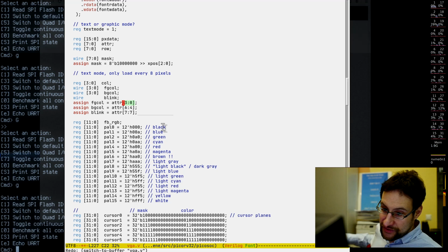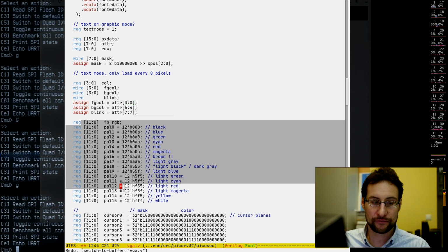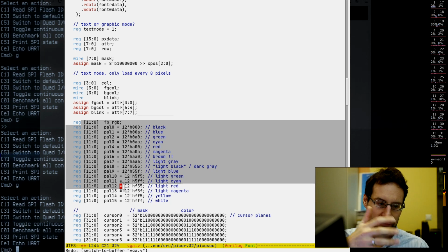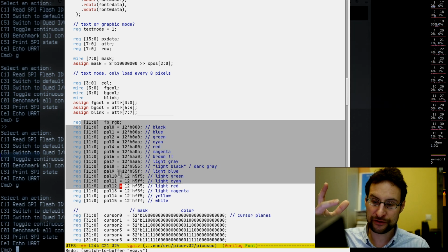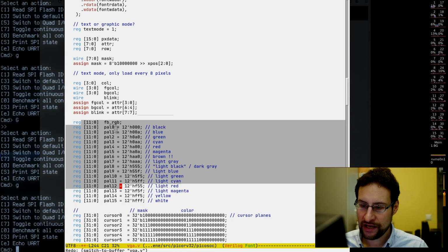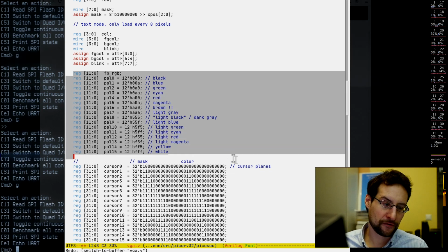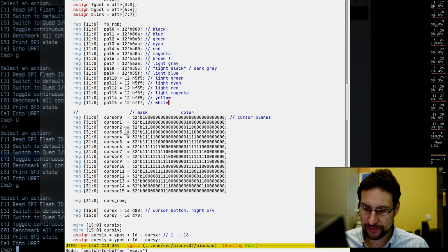Then a lot of registers, and I optimized them already as per the previous video. Initially I had some 24 bits, but we only have 12-bit color output anyway, and usually only run 16 colors, of which we can only output 4 bits anyway, so I halved them all in the previous video already, to save half of all the logic elements here. Why waste them if they are invisible anyway?